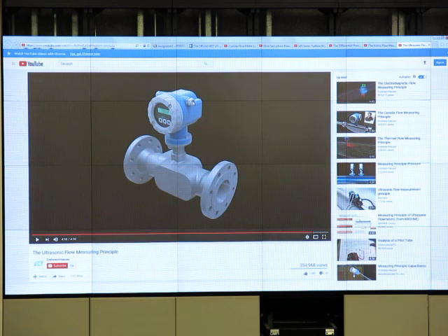What is the working mechanism for this? The point is to know the working mechanism of each kind of flow meter, and you should know that, okay? The working mechanism of this is measuring the flow rate based on the difference in the time required for the sonic wave to travel. The transit time for the wave going along the flow direction will be less, or the wave travels faster. When it goes in the opposite direction, it travels slower. Based on that difference, we can know how much the flow rate is.